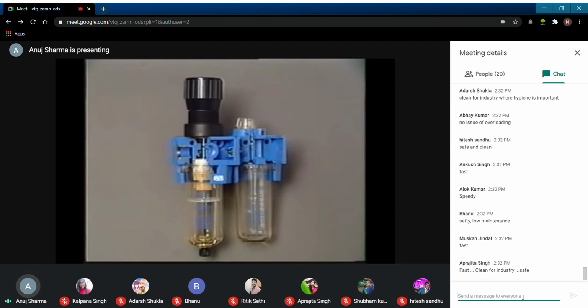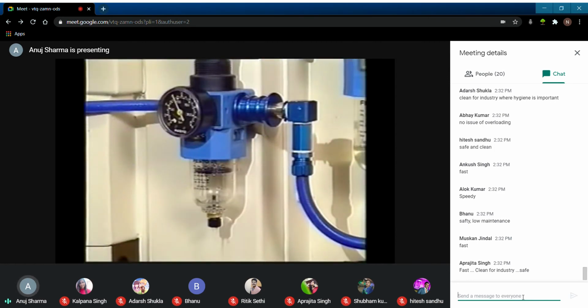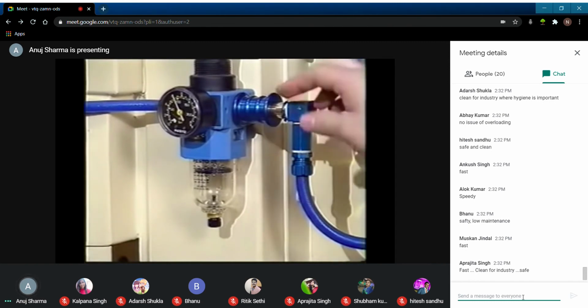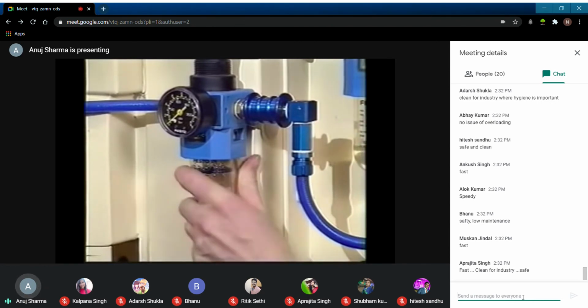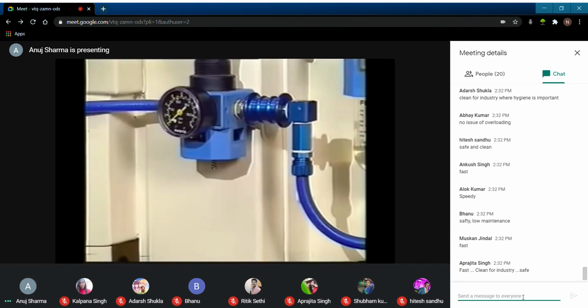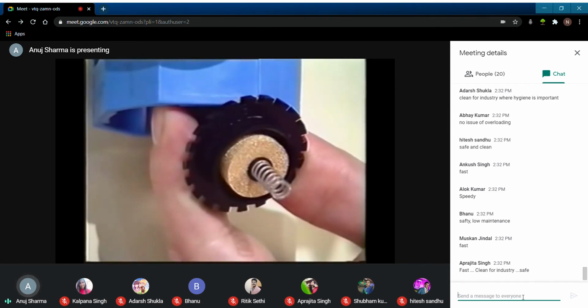This is a cutaway of a typical service unit. It has four main features. Let's identify each one. It contains a filter element, condensate bowl with drain, pressure regulator, and lubricator. In addition to removing particles carried by the air, such as rust, the filter also removes moisture. The moisture is collected in a bowl attached to the regulator that should be emptied on a regular basis, then removed and cleaned. The filter element should also be replaced when it becomes coated with dirt, such as rust particles.